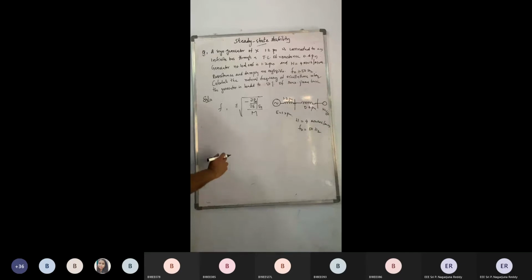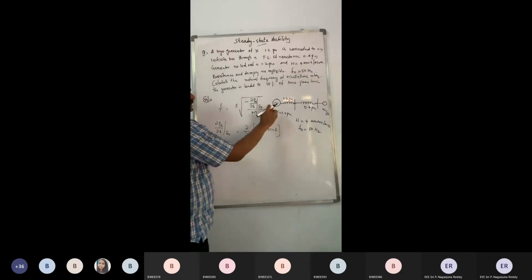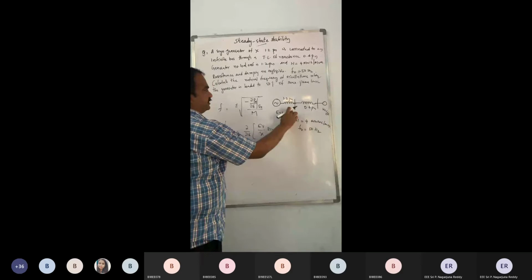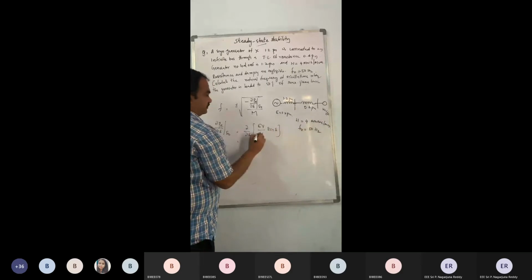What do we need now? We need dou PE by dou delta at delta naught. What is dou PE by dou delta, guys? PE you can write as EV by X sine delta, where E and V are the two ends. I am considering this and this as the ends, so the reactance is the combined one.